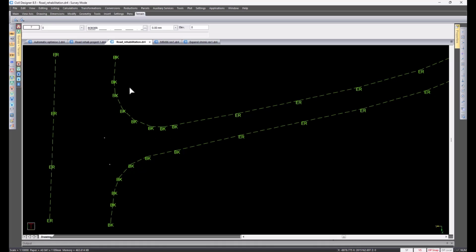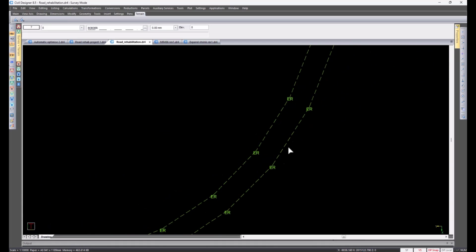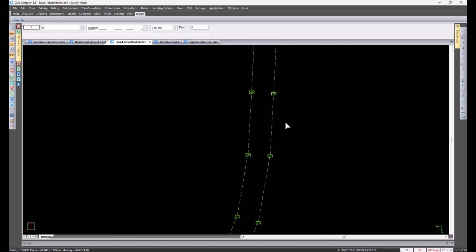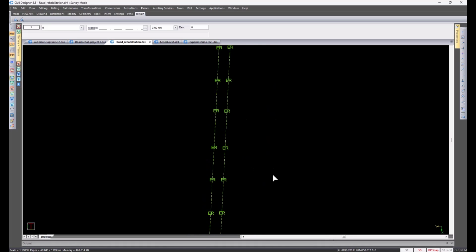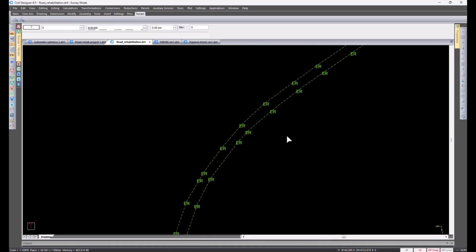Okay, so these points have already been linked up with break lines, but we need to check that these lines are connected. So basically I want to define a CAD line, and the way I'm going to do that is I'm going to use the terrain strings. I'm going to create a point string, which joins up points and the break lines. The alternatives, which we've looked at in previous webinars, is that you can use the draft expert, for example, in combination with IntelliLines. You can draw in these lines, but in this case the triangulation has already been done, so I'm going to use a terrain string.